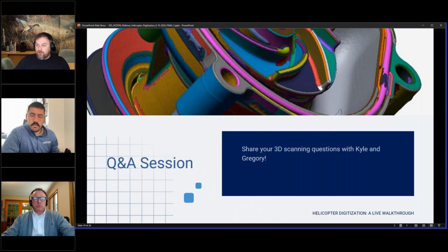The arm has its own coordinate system, and obviously you can scan in there. And then the NimbleTrack has a coordinate system, where it's the base of wherever you started from usually. And we can actually use the geometry to put the scans together if you were trying to align data from 2 different sources. Sometimes people ask that, whether they want to have data from 2 different kinds of devices. So we can align those inside of Design X. That's another assumption I'm making as well, if that's what you're trying to do, that's another possibility.